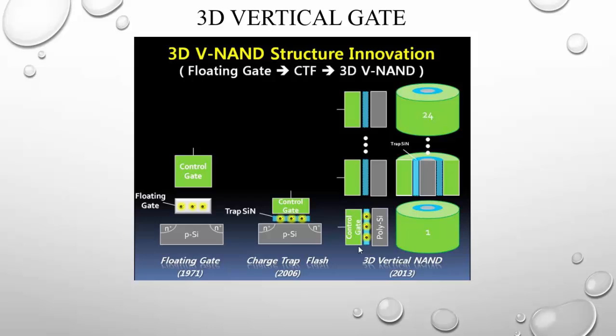Oh wow. Okay, so charge traps are also faster to program than conventional floating gate flash. Samsung claimed that its 3D NAND charge trap supports twice the write performance of a sub-20 nanometer planar floating gate NAND flash memory. Although a subsequent release said that the sequential and random write speed of a V-NAND based SSD increased only 20%. All in all, charge trapping is a good technology, and it's something of a surprise that it hasn't found more widespread use in planar flash design.